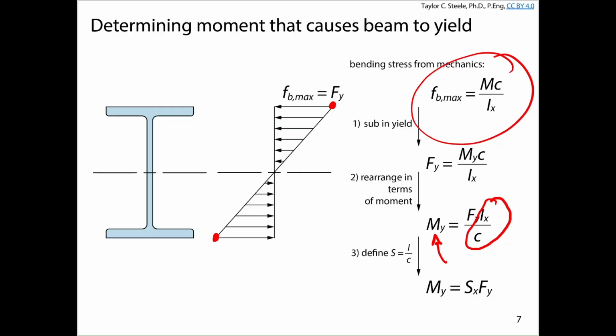Does anybody else have any comments or thoughts that they want to share? So when we designed our tension members, of course we could have let our braces at the cross-section reach the ultimate strength. Part of the problem with that for our braces was once the cross-section yields, basically it's going to stretch uncontrollably, and that can cause lateral instability issues, and that's a problem. But we did let the cross-section reach the ultimate strength at the connection.